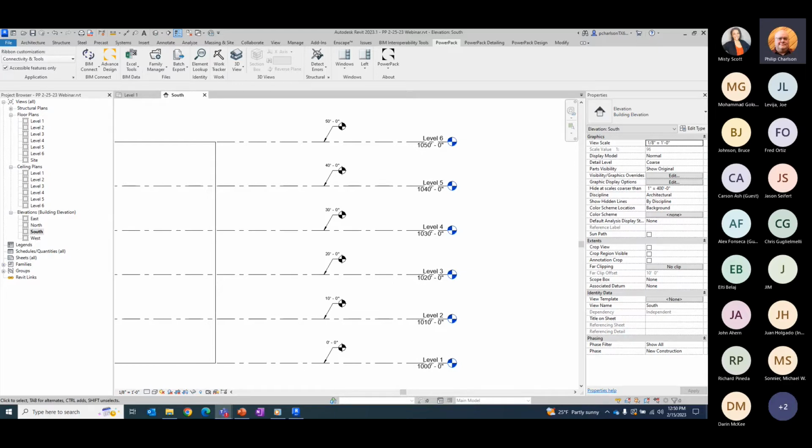When you're creating a few different parameters, don't wait until you get close to the end and then start flexing it and find that, oh shoot, there's some issues with it. Now I've got to dig back in and figure out where that issue happened. So I always push people to flex often to make sure that those parameters are working properly.